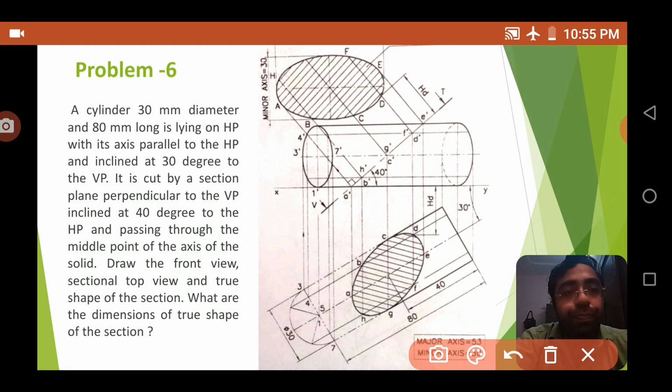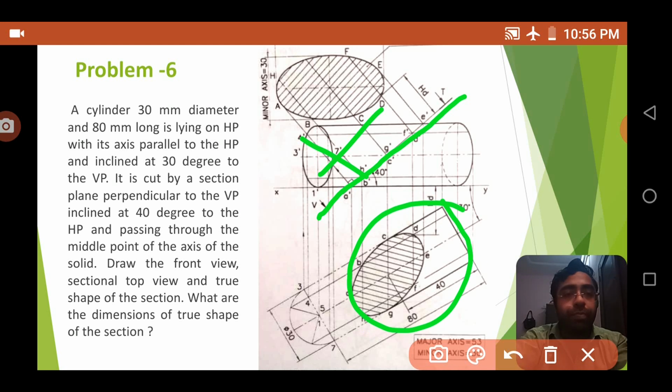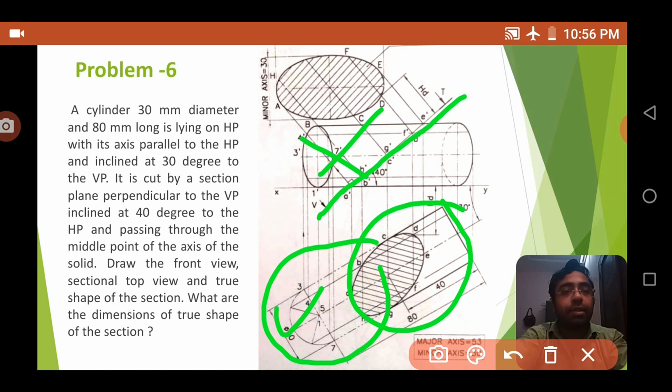Now, as you know, when this cutting line is passing through a pipe, this portion won't be available there, so it is not there. So you have to remove that portion. While removing this portion, only this portion is available. So the balance you have to draw as continuous thin lines, and the dashed lines you represent as continuous thin dashed lines.